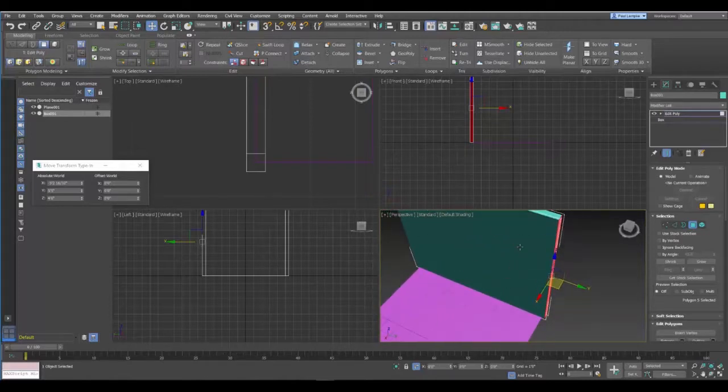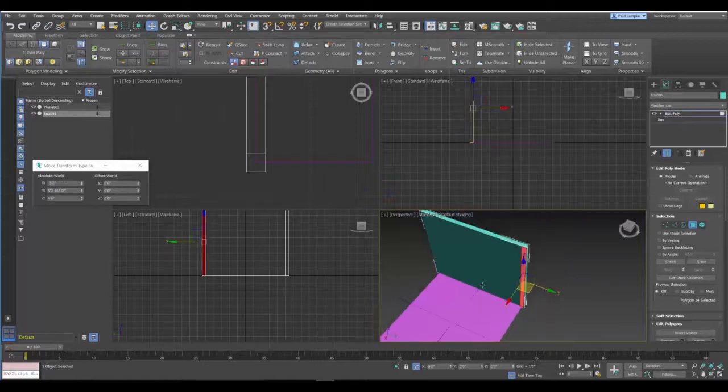So I have a solid wall. Now I'm going to make a wall that has a window in it. So I'm still in this box modeling mode where I'm extruding faces. And here I know from my dimensions that there's a window in the center. And this is a 10-foot wall, so basically there's 3.5 feet, then the 3-foot window, and then another 3.5 feet.